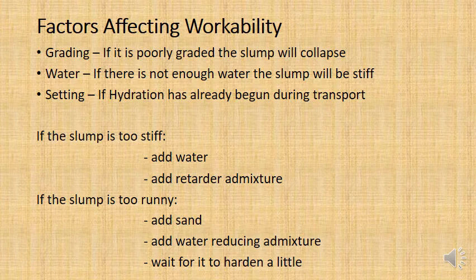Well, the other reason is because of workability. If it's poorly graded, meaning that most of the aggregate particles are the same size, the slump will collapse, and that will lead to a much weaker concrete. It also will lead to segregation, which we will talk about in the next slide.